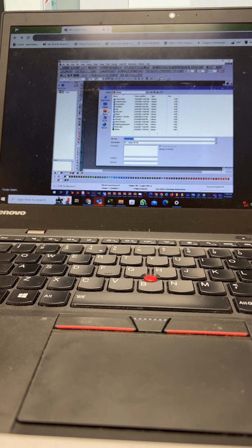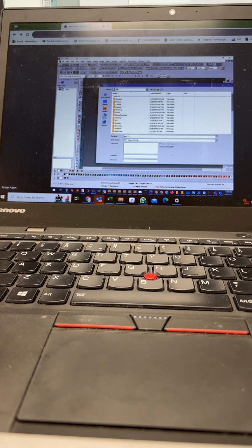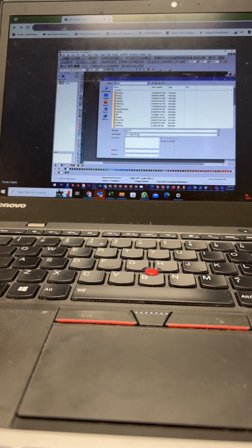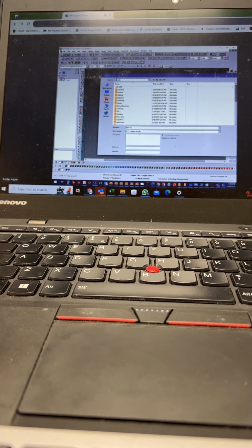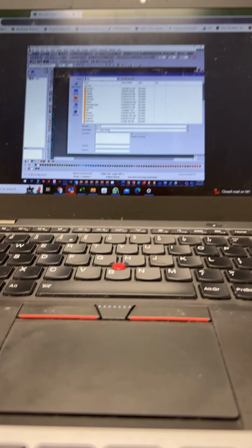Customer can put their files anywhere they want. The default directory is the jobs folder. The default file type for Gerber is PLT. That is different than the HPGL PLT. It is a Gerber proprietary format. Stands for Gerber plot file.